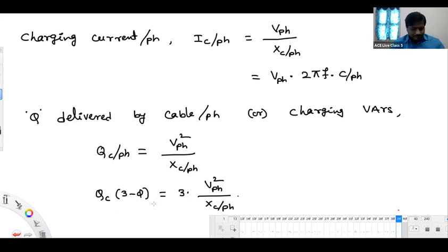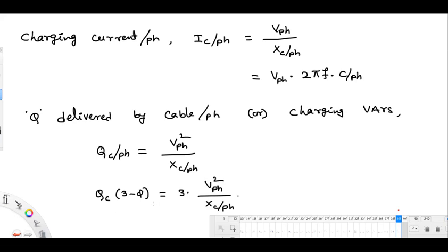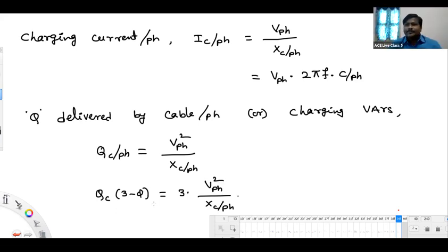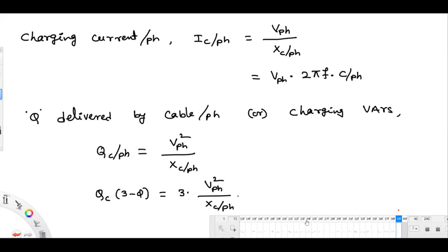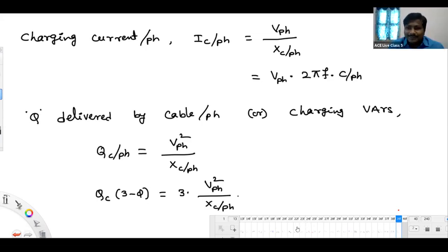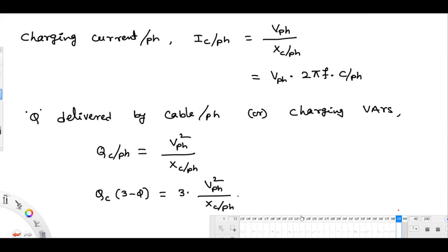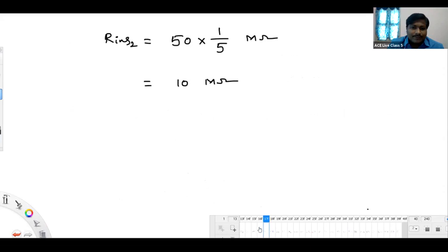What's your doubt? Sir, the electric field intensity on the core will be maximum, no, sir? Where we are taking r/R equal to 0.368, that is the maximum value. That is the maximum field intensity experienced by the dielectric material for that dimension.